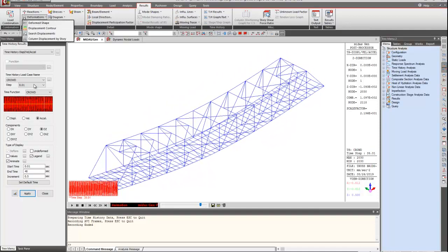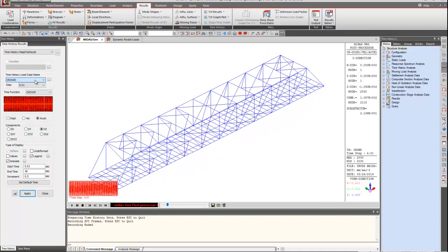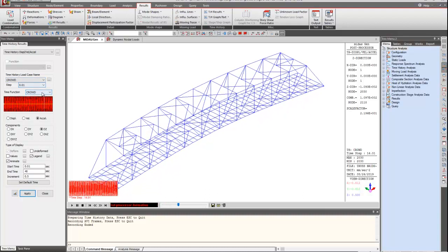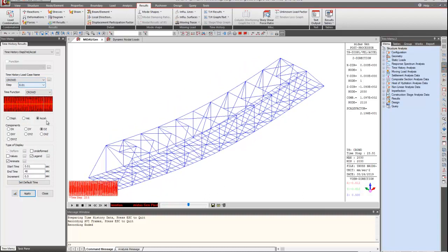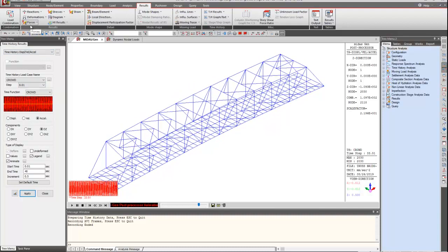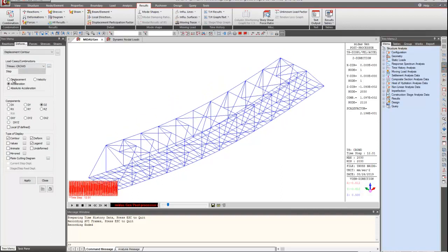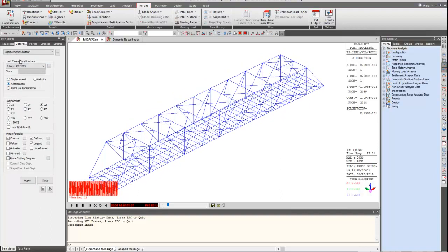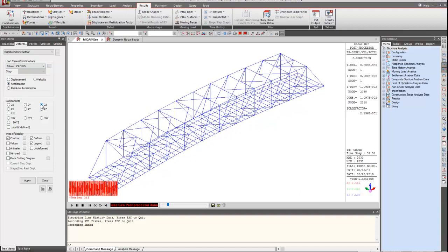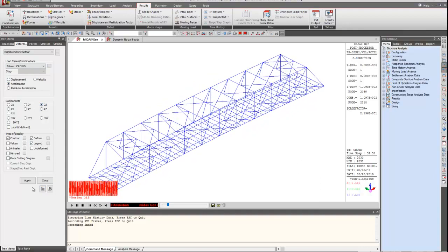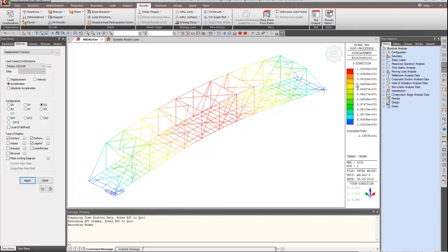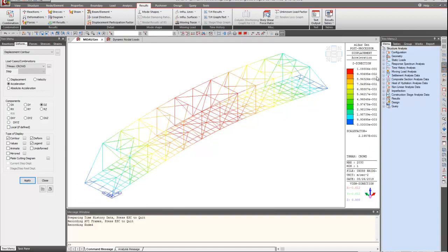So similarly for other load cases, for jogging and walking, for crowd condition, for different steps, I can see the results. Okay, so let's see the maximum acceleration in dz direction for THmax crowd. So now here we can see, let me change the unit to meter. Yeah, so we are getting it as 0.11 meter per second square.